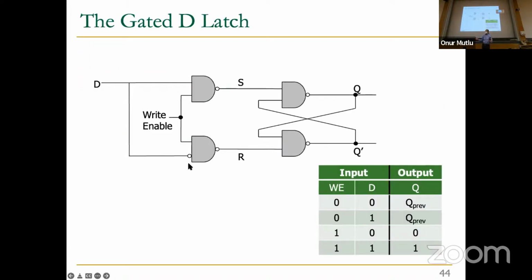Any questions on this one? Yes. Excellent. Basically, I think your bigger question is this metastability issue. Can that lead to a random number generator? And the answer is yes, absolutely. Assuming that the variation in the circuit is random, then you can actually generate random bits that way. And this could be one way of generating random numbers. There's actually a lot of literature on that topic.